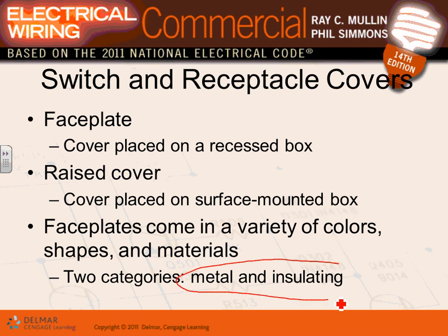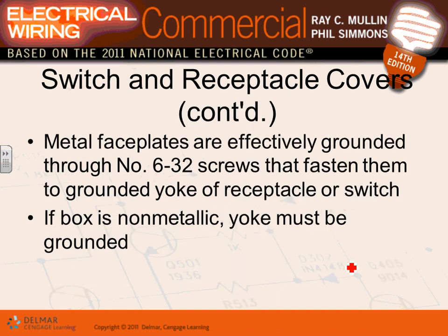When it comes to the plates, guys, the most important thing, look at that there. You can either have it metal or insulated. Most of the stuff in a commercial building is insulated type. If you go to an industrial building where there's a lot of abuse, the cover itself becomes metal. Metal faceplates are effectively grounded.